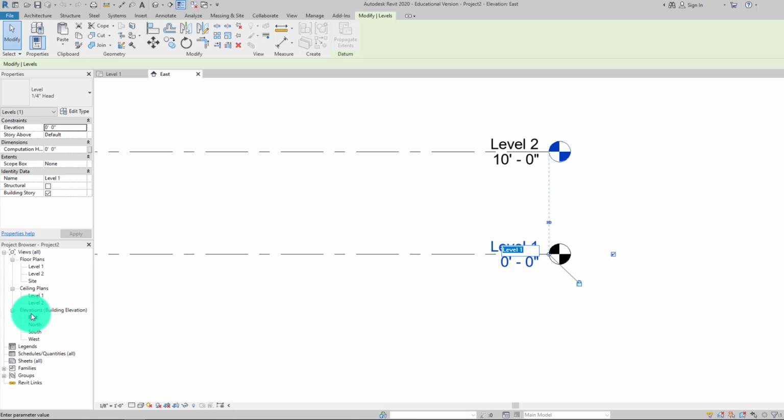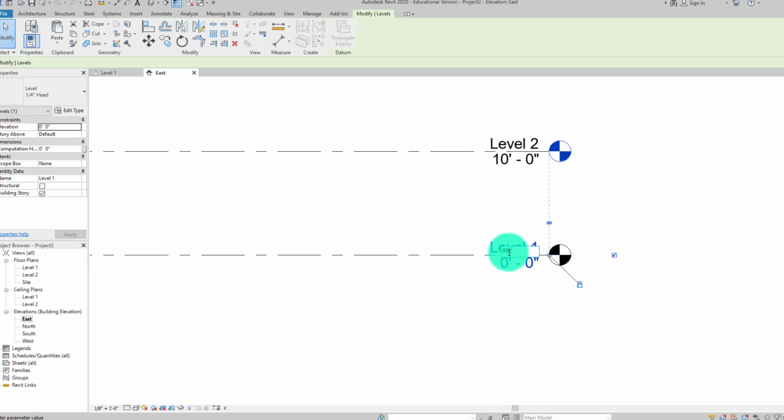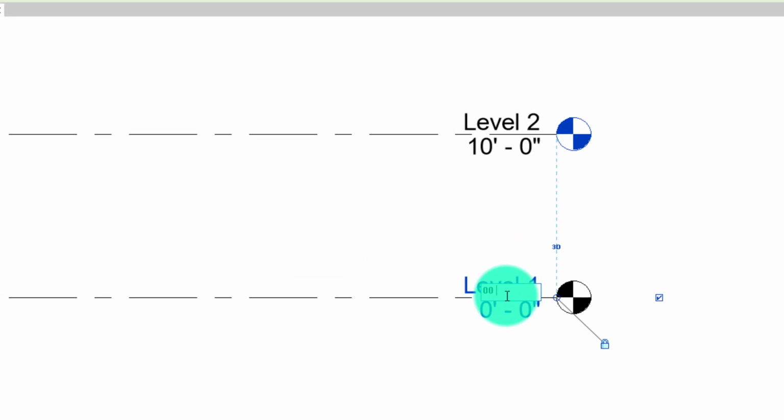because this will be placed in alphabetical order over here, I always like to name my first whatever it is 00, and then 01, and then all the way up to 09, and then you do 10. And the reason why, because if you ever have more than 10 floors, if you just type 1 2 3 4 5 6 7 8 9 10, once you get to 11, it'll place it all the way back before 2, which is why, really quickly, that's why we do 00.